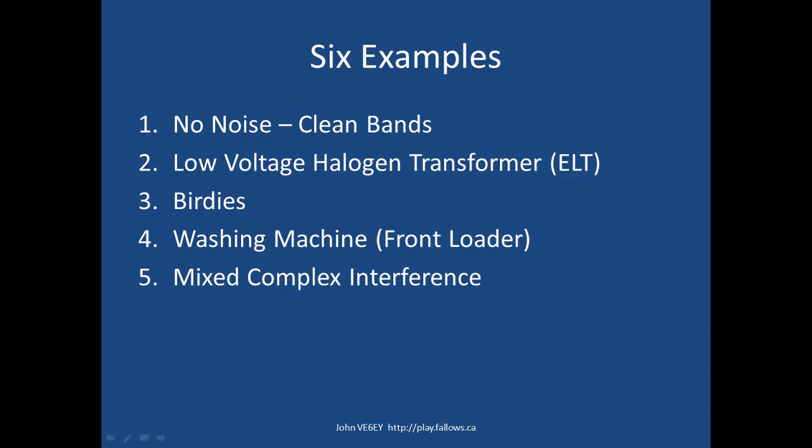So if anyone ever tries to convince you that these noise cancelers don't work, I hope these videos have convinced you that they do work. You'll notice a lot of the signals that I was clearing up so that I could hear were quite weak, down around the S2 to S3 level. I was able to reduce the noise enough to get good copy. So I've saved the most dramatic example of how well these things work till last. Here's a short clip of some 15 megahertz shortwave broadcast with some very nasty interference, and it's pretty well cleared up on the frequencies that I'm listening to by the ANC-4.